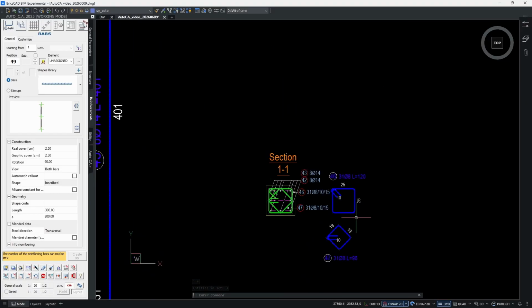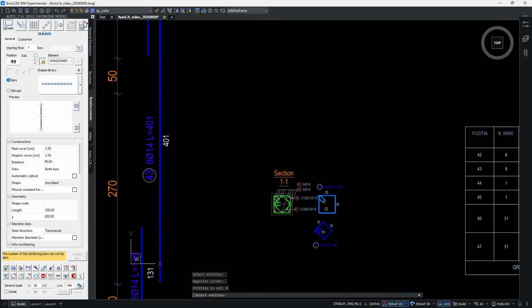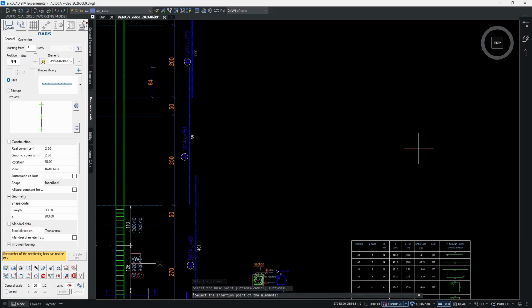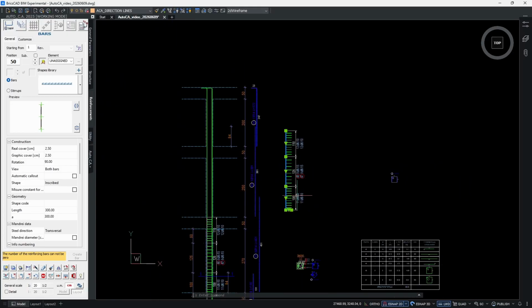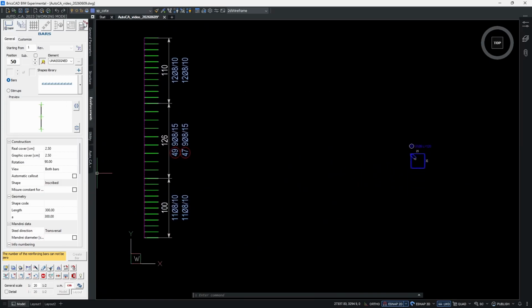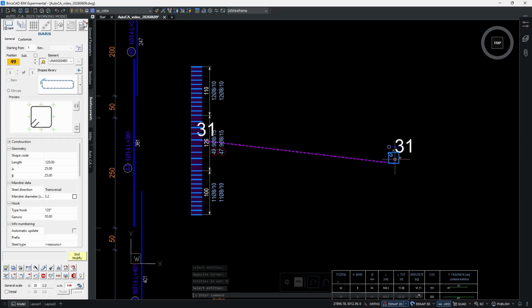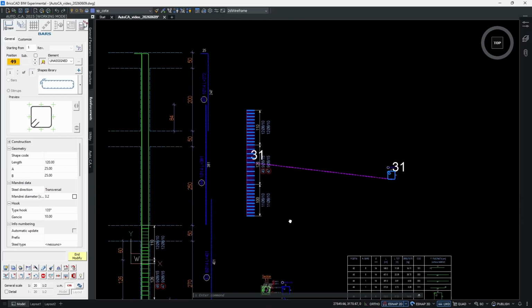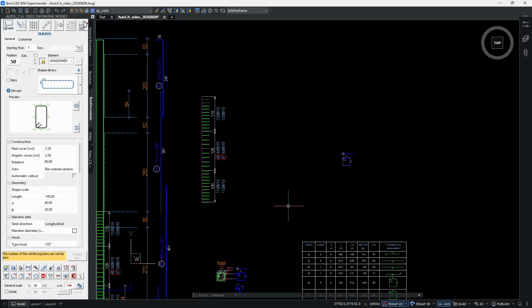And if we copy both of them, both the internal bar series and the external stirrup, then I'm gonna get a brand new stirrup with the same amount as the original, because now we have a new link between these two. We modify the outside stirrup. You can see that it's not linked to the original bar series, but the new one. So we can say that the links don't disappear with copying. So you can keep that in mind.